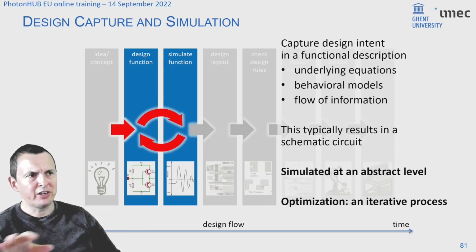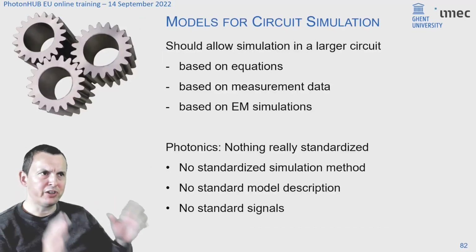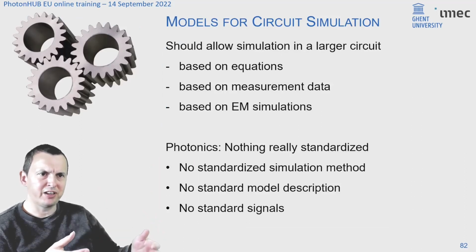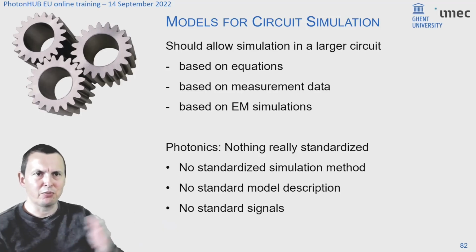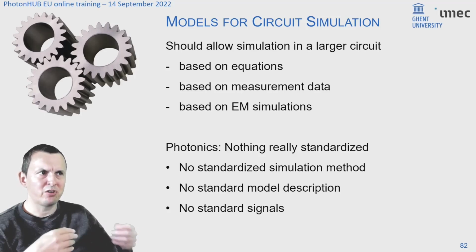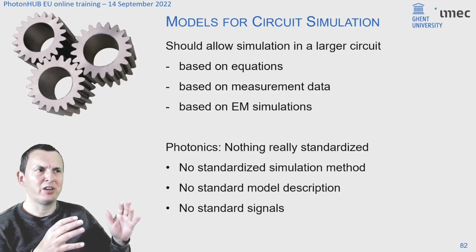Now, here photonic circuit simulation is slightly different than electronic circuit simulation. First of all, we're talking about circuit simulation. So whatever method you use, you should be able to put a fairly large circuit in it and do it efficiently. That means that the traditional photonic simulation methods that people use, like FDTD, are totally out of the question. You basically need something that's based on equations or based on data, that has behavioral models that mimic the physics inside each component, but without going into full electromagnetic simulation.